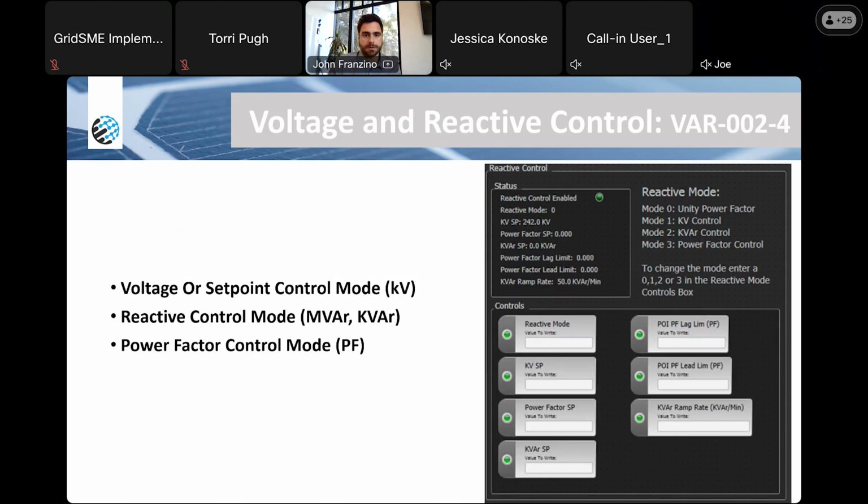So make sure that when you're working with SCADA integrators and asset owners, if you're the GOP, you have good visibility and understanding of AVR and have alarming set up for if that status ever changes, and understand who you notify from a TOP standpoint if that status changes, within 30 minutes.